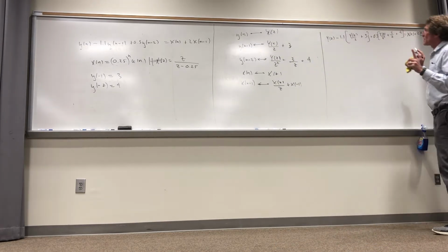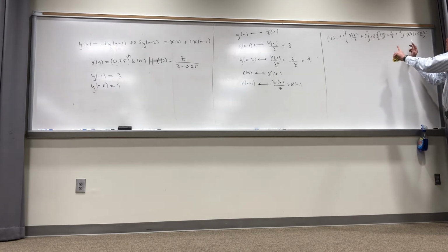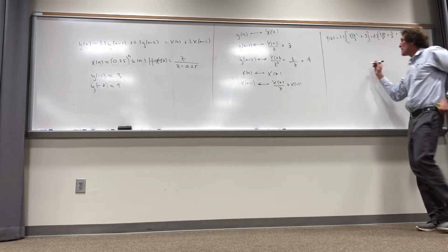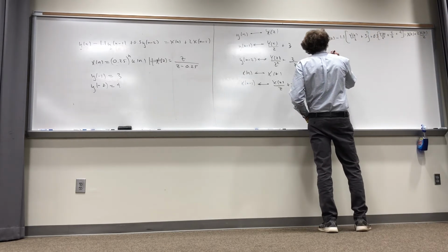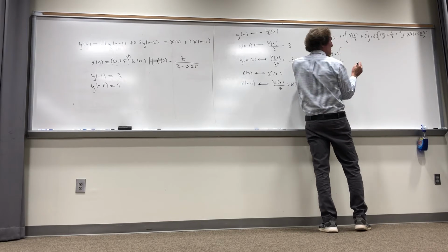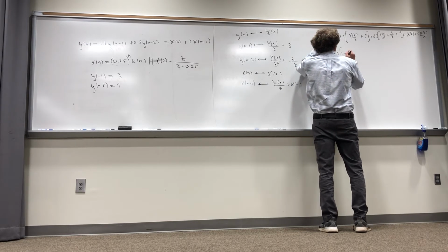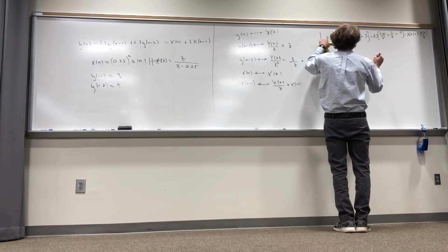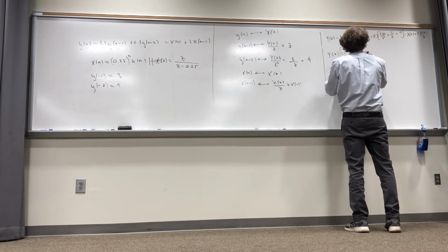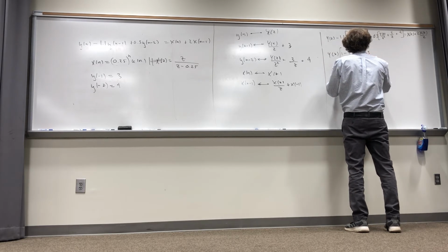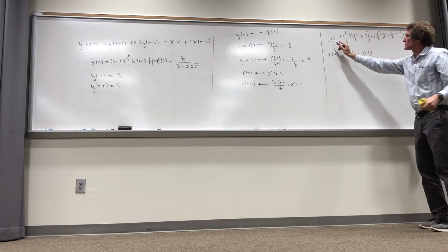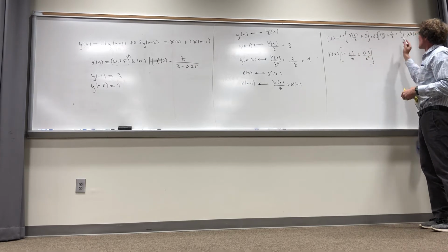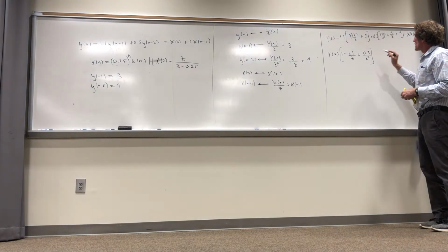Now, the next thing I'm going to do, listen to me carefully, I'm going to break out y of z by itself with all its coefficients. So when I do that, what do I get here? I get y of z times, just follow me, 1 minus 1.1 over z plus 0.3 over z squared. Now what I've done is factor out the y of z here, brought this constant, 1.1 over z here, and then I took y of z out of that one and got 0.3 over z squared there.